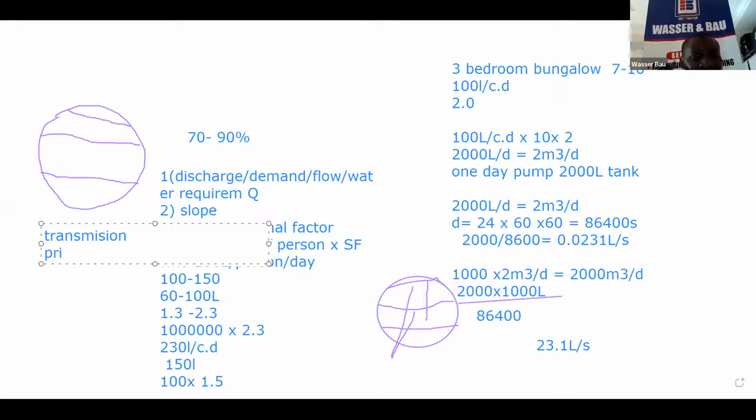Now, in water recirculation, if you get the primary pipe wrong, then you have rubbished the system. Let me give you something that happens in our houses. When you have water on your tap, your neighbor will not have water, even though I'm guilty of it also. The ideal pipe size to bring water into a house is a 2 inch pipe from the mains.